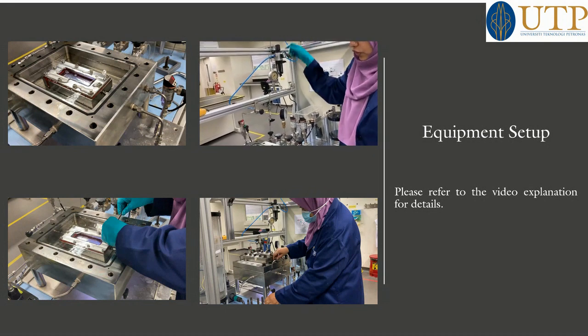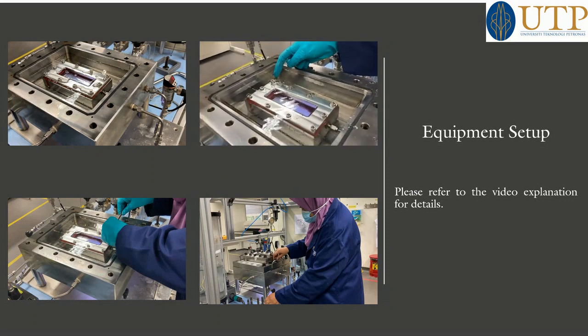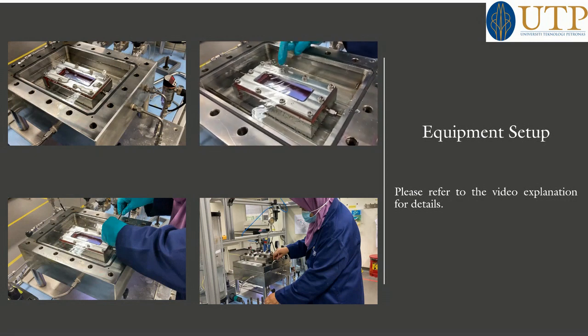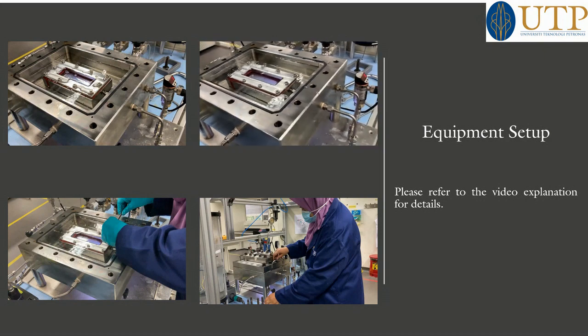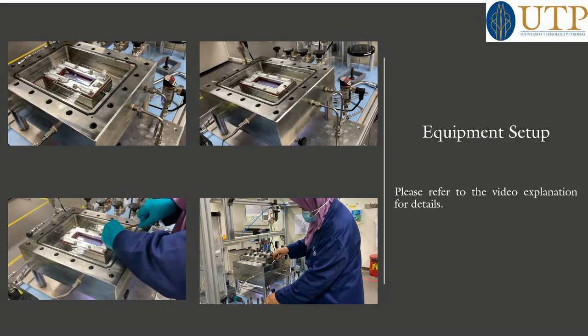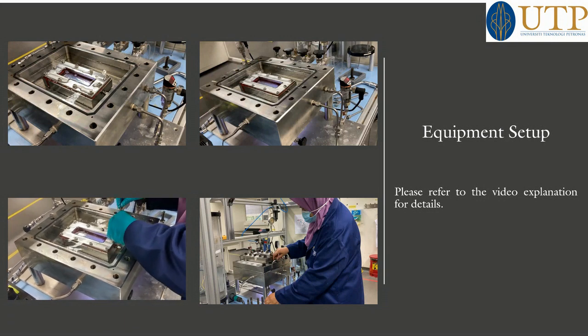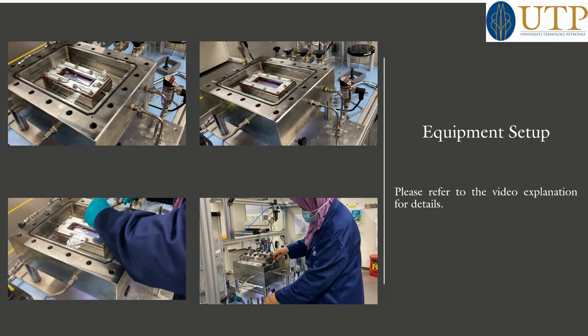You can see there is a lot of bubbles coming. That means in these places there is leakage. So make it tighter, tighter, tighter.